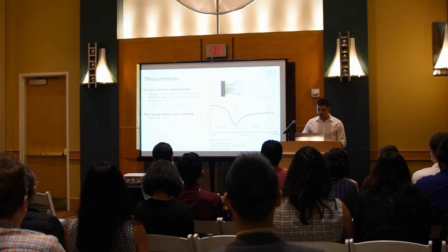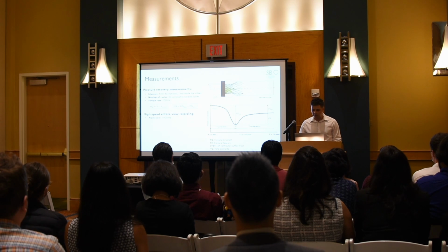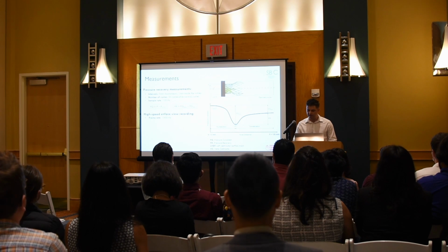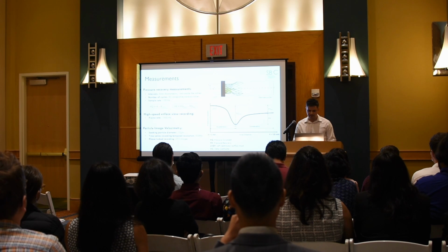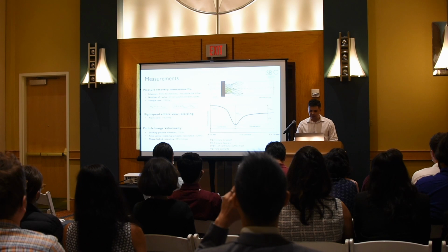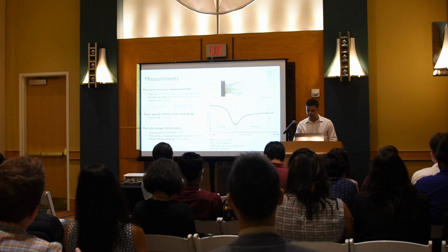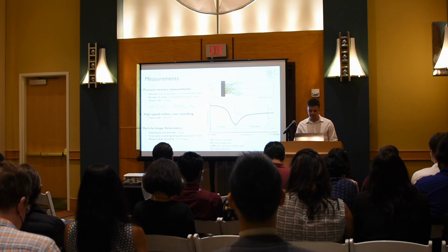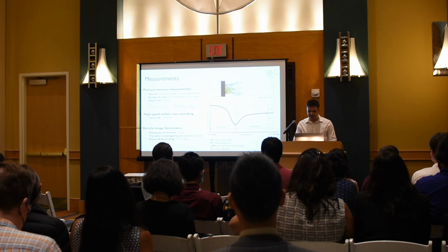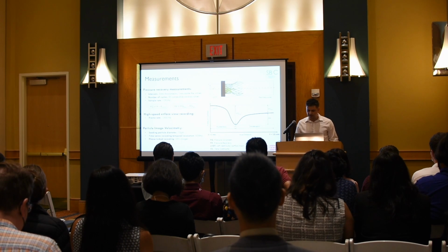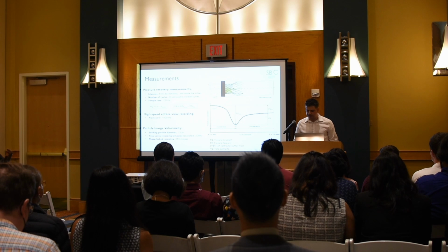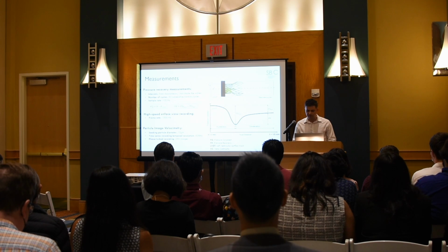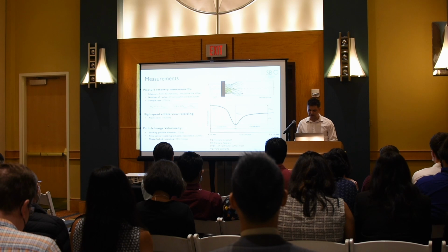We also recorded a high-speed recording of an en face view of valve opening and closing at a frame rate of 1000 Hz. We also performed particle image velocimetry to assess the flow downstream of the valves. The flow was seeded with fluorescent particles with an average diameter of 10 microns, and the time series recording was acquired at a temporal resolution of 500 Hz, and the phase lock recording was acquired for the sake of statistics.